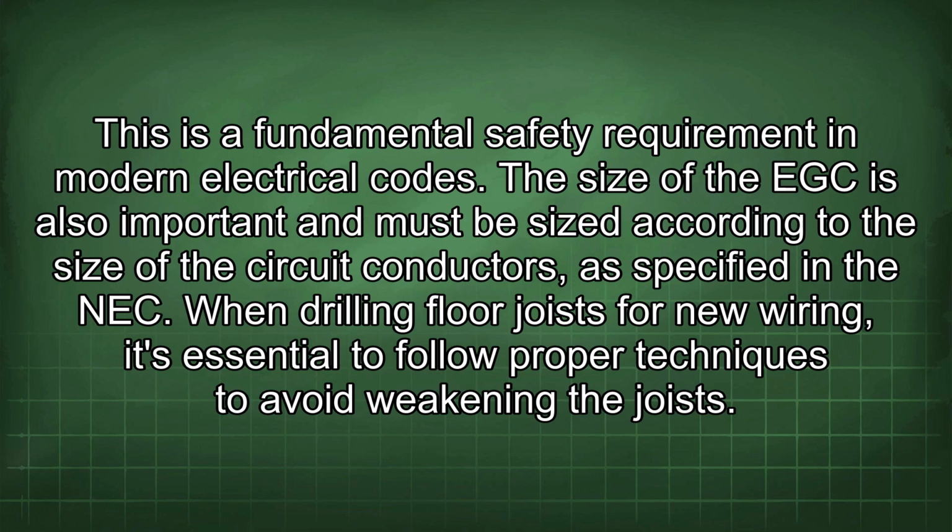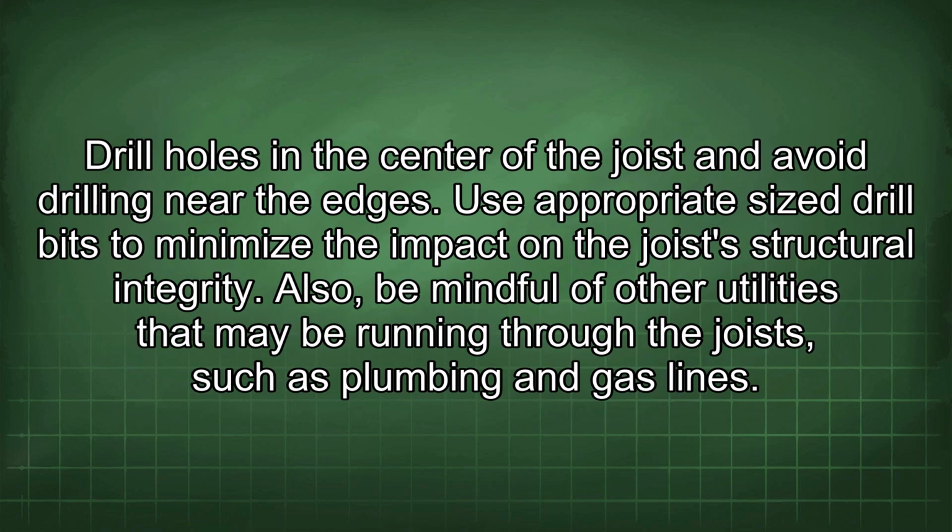When drilling floor joists for new wiring, it's essential to follow proper techniques to avoid weakening the joists. Drill holes in the center of the joist and avoid drilling near the edges. Use appropriate sized drill bits to minimize the impact on the joist's structural integrity. Also, be mindful of other utilities that may be running through the joists, such as plumbing and gas lines.